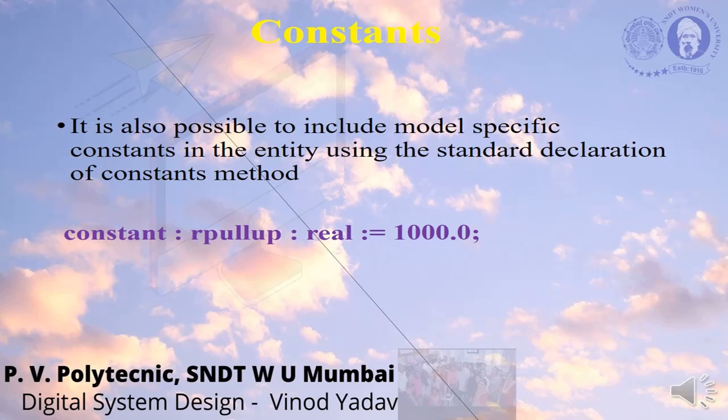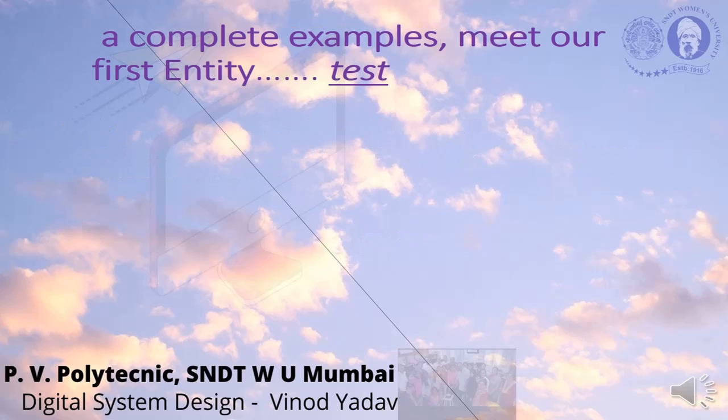After that, the complete model where we will be defining the port. We'll write entity test is, end entity test. This is the standard way. Whenever we define an entity, we have to define it between these two. The name of the entity is test, and you can end it as end entity test, or just write end test.